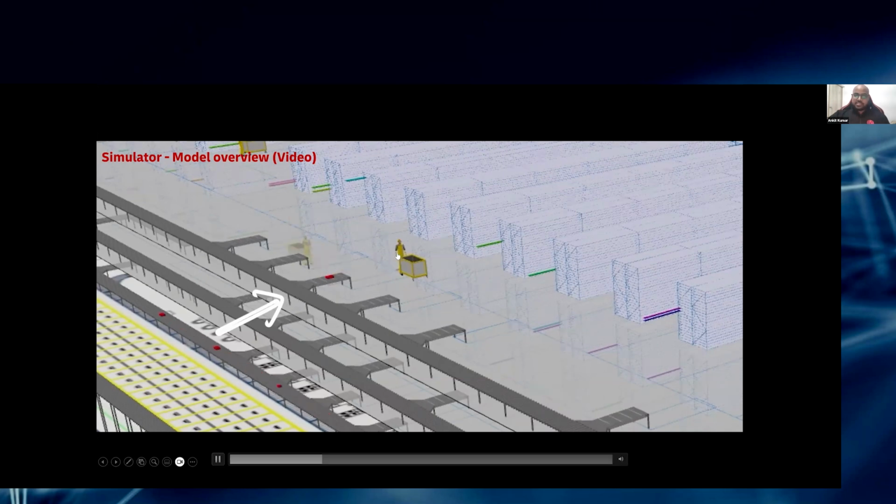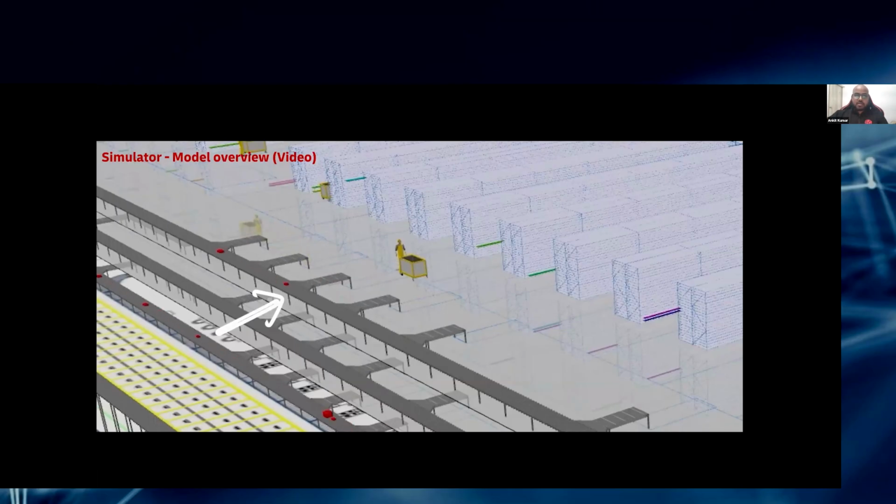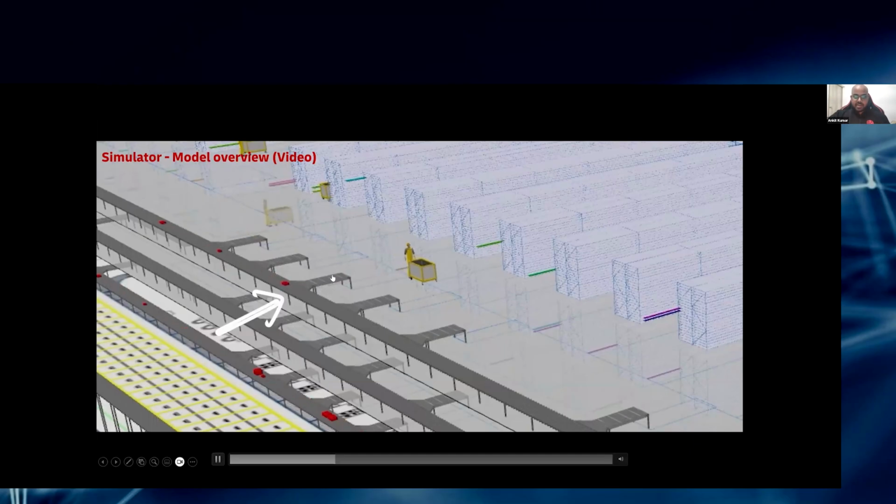After reaching the VAS station, he will scan all the cartons and identify whether any value-added services are required or not. And then he will drop all the cartons on the conveyor. There are two possibilities for the cartons. Either they could go to the end shipment sorter or to the next level. If there is a possibility of more items to be placed inside these cartons, then they will be ejected out to the next level. And after dropping all the cartons, the picker will go back for the next task. So this is how a task starts from the top level, and it will go to the next levels if more items are to be kept in the particular carton.